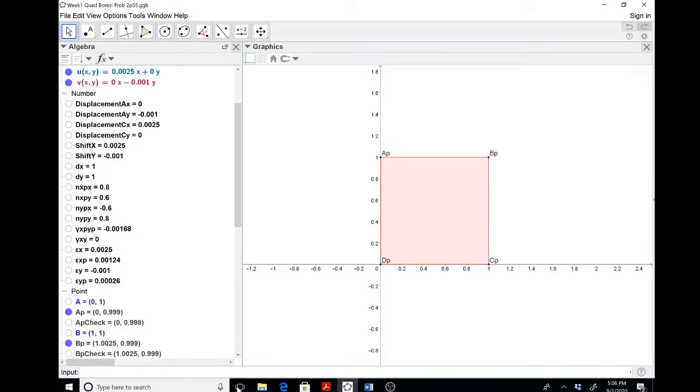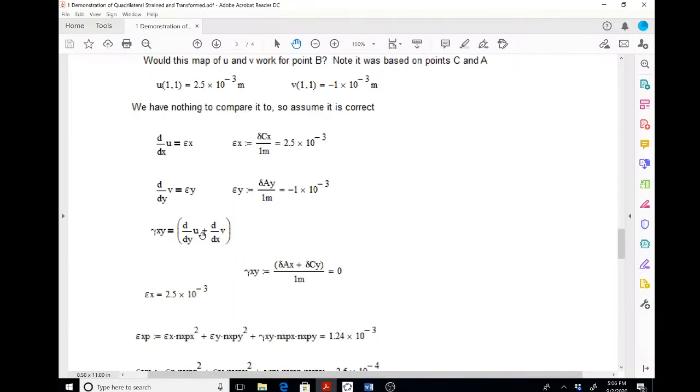And then the gamma is the movement in the u direction divided by y. So that's the two angles of the racking or the distortion of the element. du/dy plus dv/dx. So you take the opposite one here.